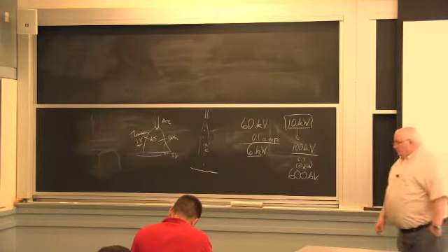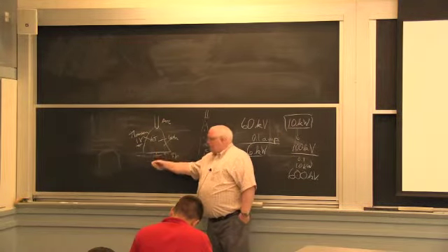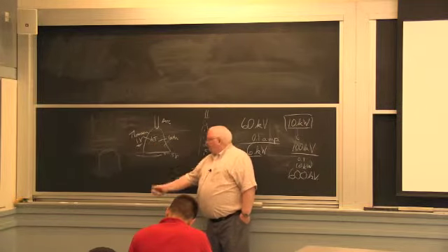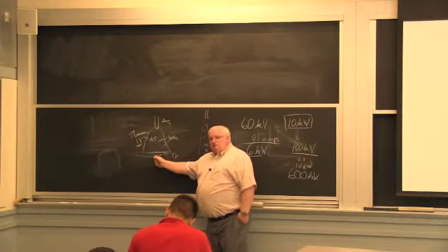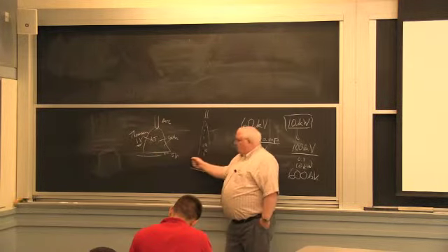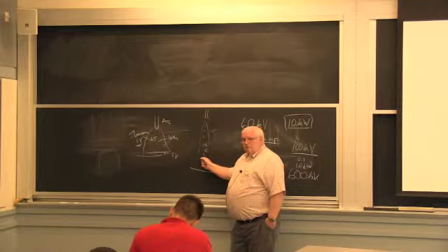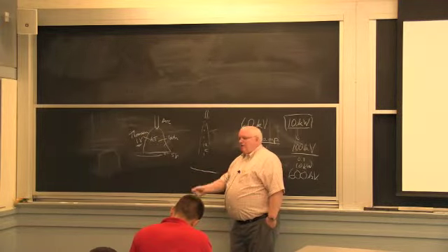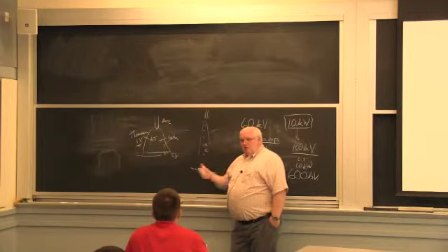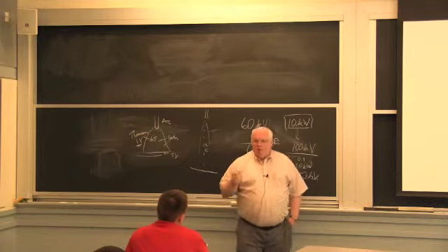The advantage is you can run an arc manually. You don't have to have a big vacuum chamber. You don't have to have automation. This is $10,000 worth of equipment to get into the arc welding business. This is $1 million worth of equipment to get in the electron beam business. With electron beam, you've got to have a very high production volume, or laser welding, in order to keep it busy. Or you're going to need a very high value added part.